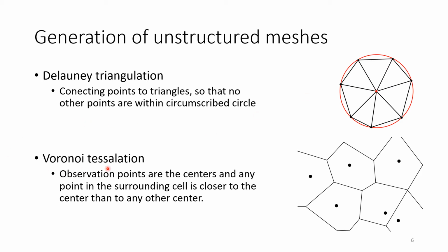The Voronoi tessellation is for a different kind of technique, we'll discuss in a second. What you do here is like an organic growth. From each point, you are growing your volume until you come in touch with the volume or the area of another point, and then you stop. This way each line is closest to the two points and further away from all other points, right? You can see this one here, those points are really close, so when they are growing, they very quickly come in contact and stop.